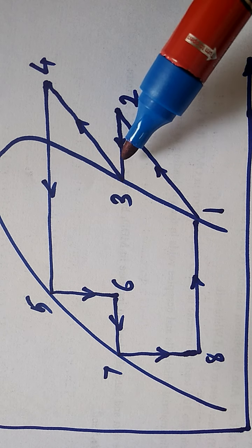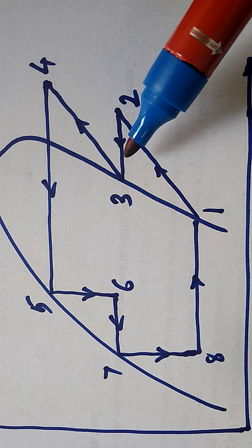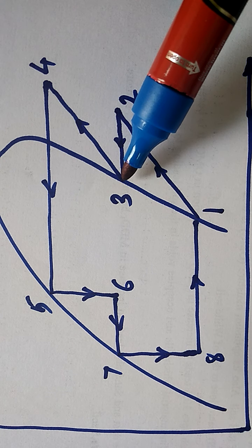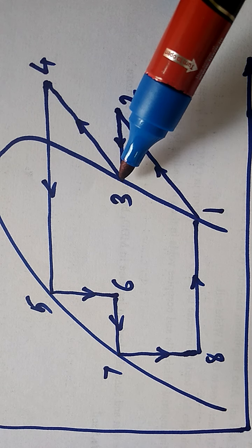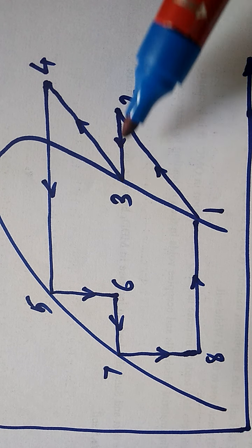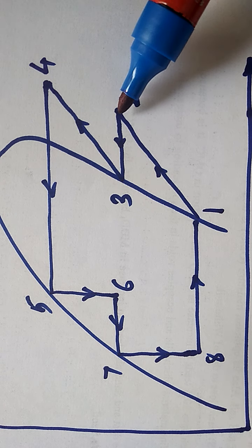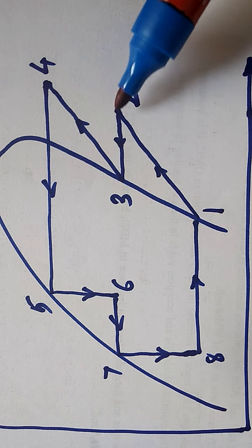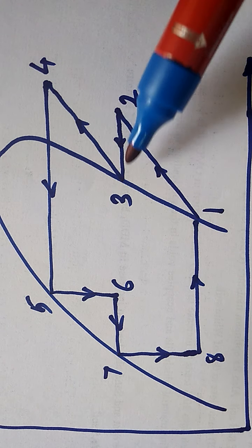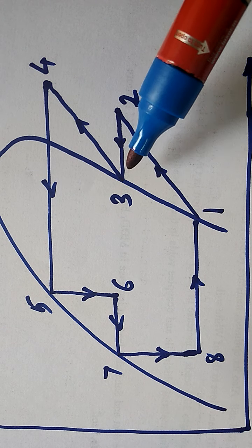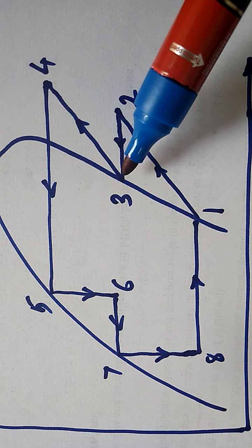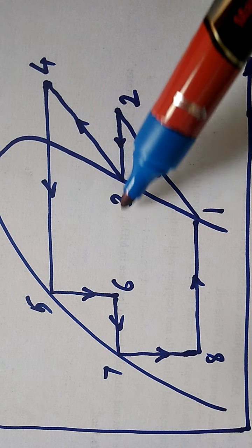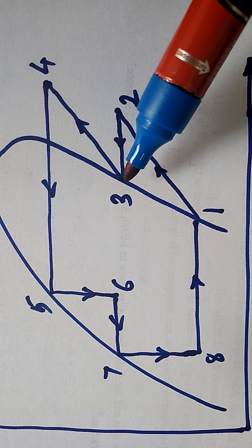This high temperature and high pressure refrigerant is cooled to dry saturated refrigerant corresponding to the pressure of state 2. So the 2 to 3 process, we can call it the intercooling process. And after intercooling, dry saturated vapor at the intermediate pressure is available.